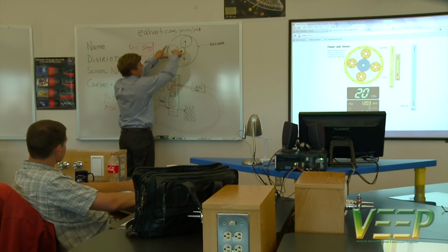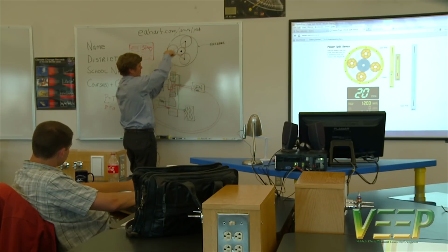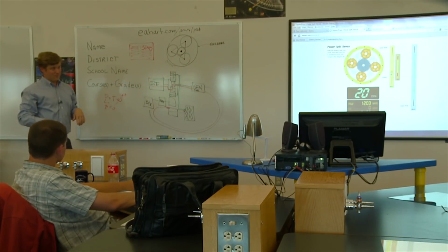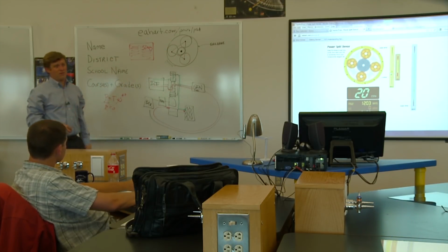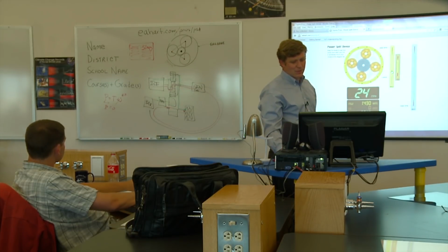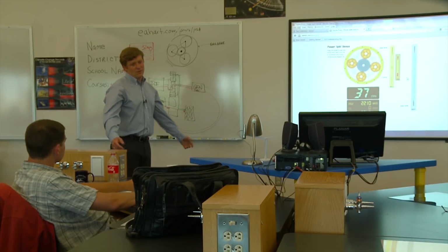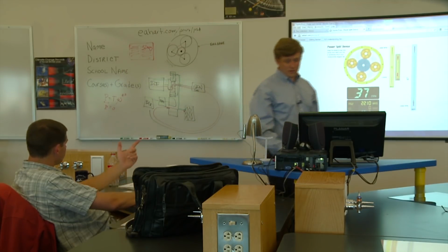This interior sun gear is spinning like crazy. The planet carrier is completely still, while the ring gear is spinning the opposite direction like crazy, all to hold the engine perfectly still. You can see that the max speed in a Prius in all EV mode is like 35, 36 miles an hour, right? So that gives you an idea what goes on there.